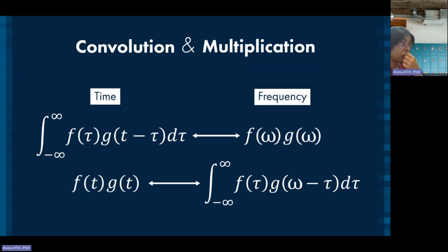So just keep this in mind that if you're doing filter design, you may never calculate the convolution integral directly, but the same concept is being applied when you multiply two frequency signals together. As this moving average example shows, we can design any number of interesting and useful filters for processing signals simply by shaping the impulse response.